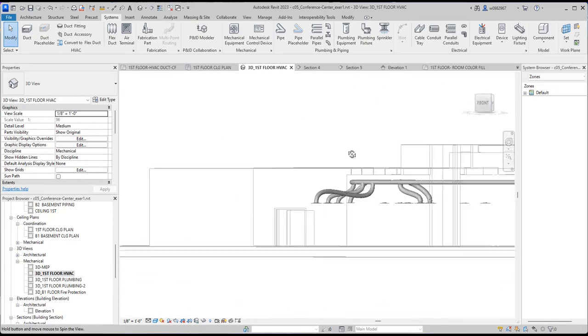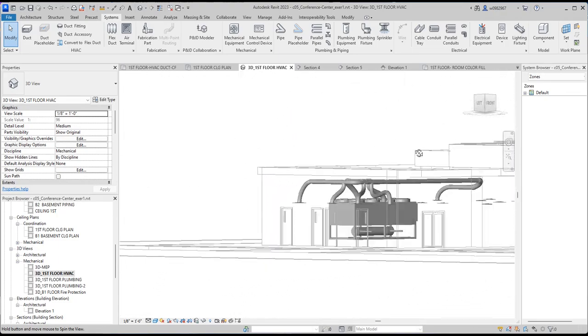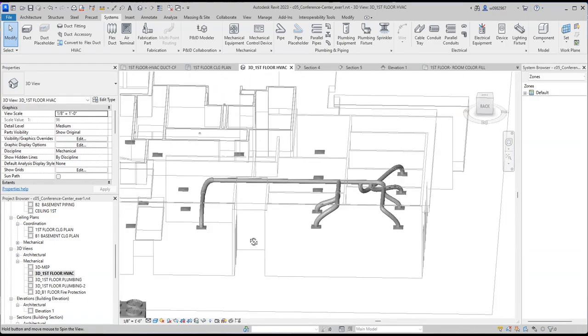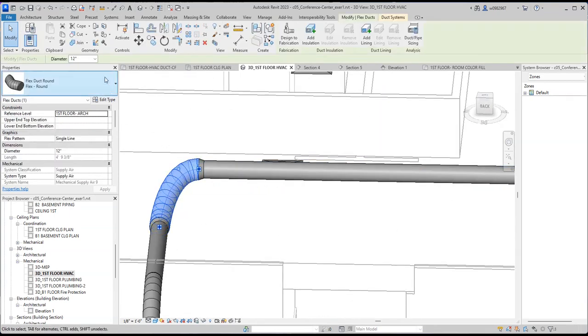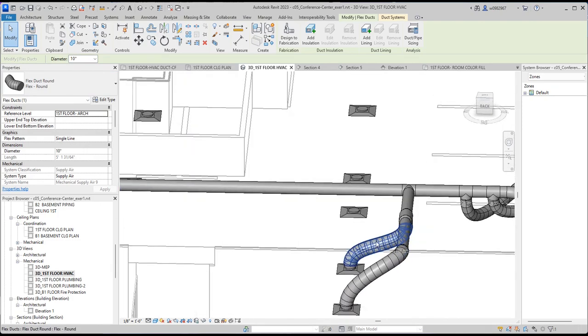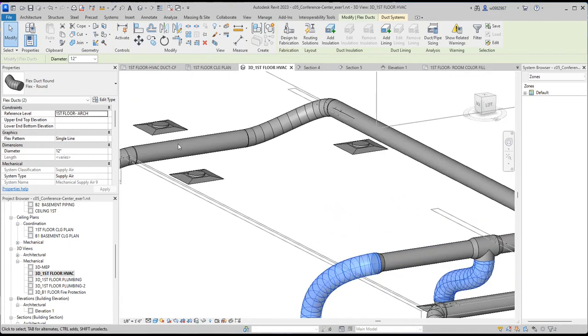It's not efficient. So you inspect your 3D, make sure that everything is connected. There's no problem. The fittings here are big because remember we didn't change this to 10. So if ductwork is 10, make it 10. You can reduce the size when you go here, but these are not 10 inches, and that's why you're gonna have this bulging thing here because you need to make this 10 inches.